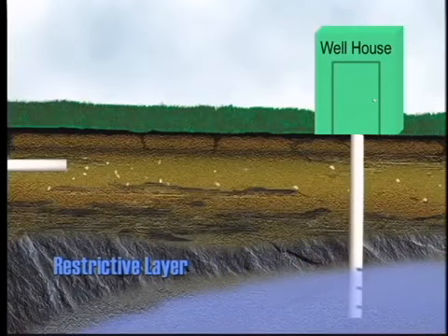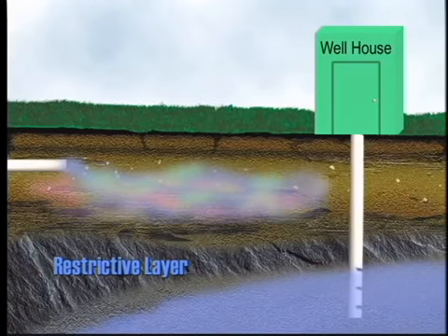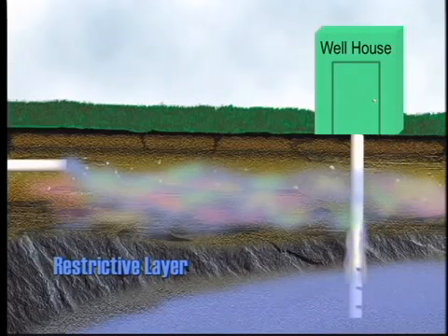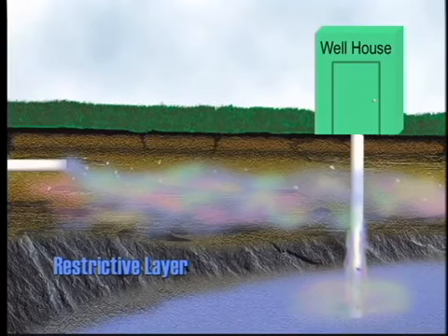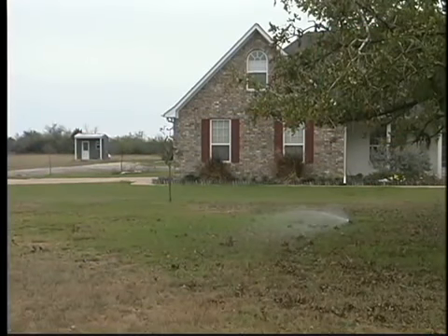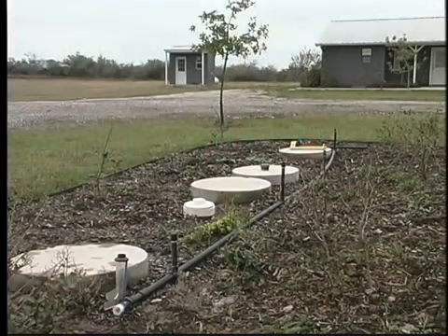Wastewater is cleansed as it moves through the soil. But if this distance is too short, the wastewater could still contain nutrients and pathogens when it reaches the well site. If the well casing and native soils have not bonded well, partially treated water can easily flow along the casing, contaminating the groundwater below. For this reason, it's important to note the location of any neighboring wells, even those abandoned or not on your property.